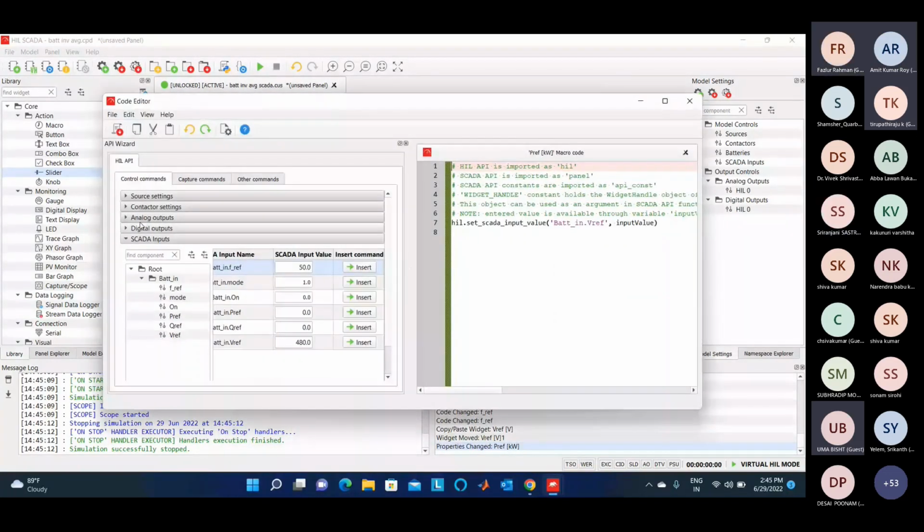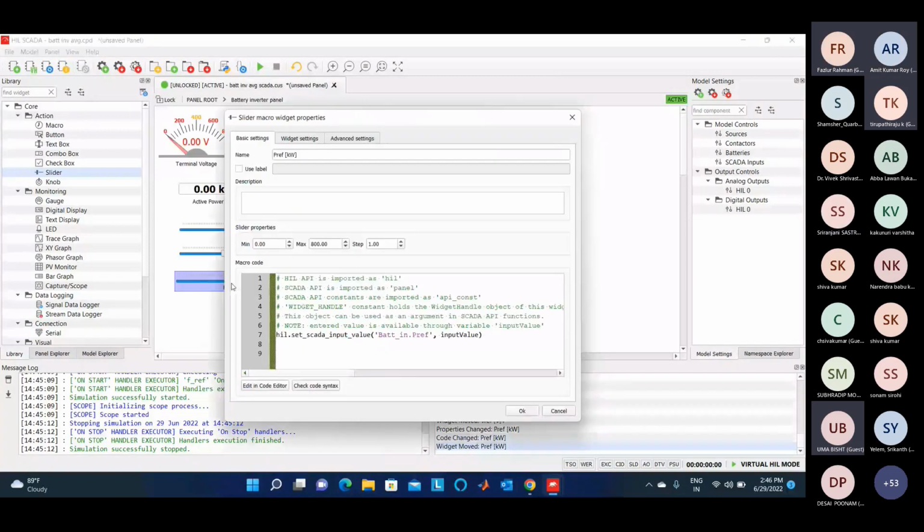First we will take it here and after that we will go. So here P reference, select this and insert this code. Instead of this, we put the input value. Save this one, close and then again open. Here taken as minus. Let's say we have taken a range of minus 1600 to 1600.